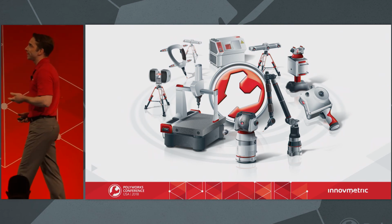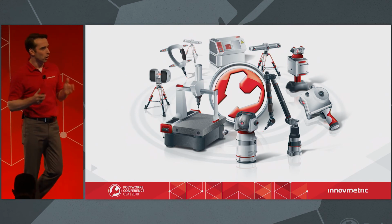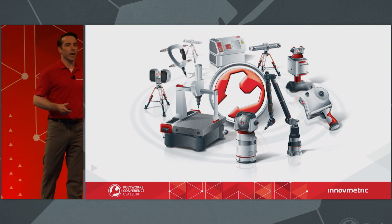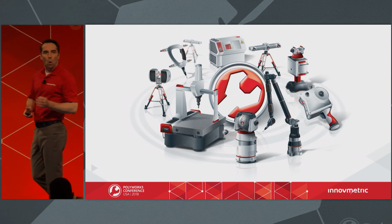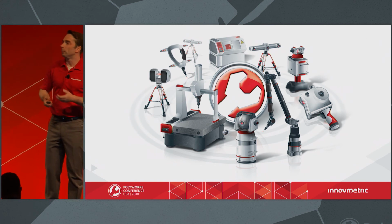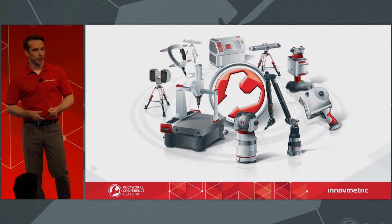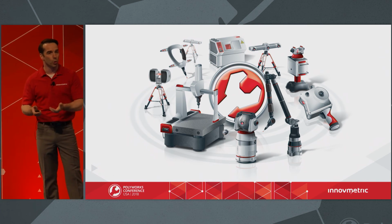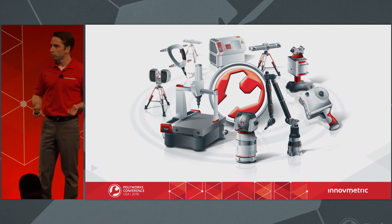Now, for example, a CNC CMM is great to automate repetitive inspection. Laser trackers are ideal to measure over large volumes. Portable arms are known for their versatility and ease of use. But this is all great, but when you think about it, in many organizations today, all these devices use their own metrology software. Now, this creates a ton of problems. For example, if you have a CNC CMM that is currently used to inspect a part and it's busy doing something, you can't take this project and bring it on an alternate device if you need to inspect more of those pieces. Or if you do, will you have to build a brand new inspection project to do so?